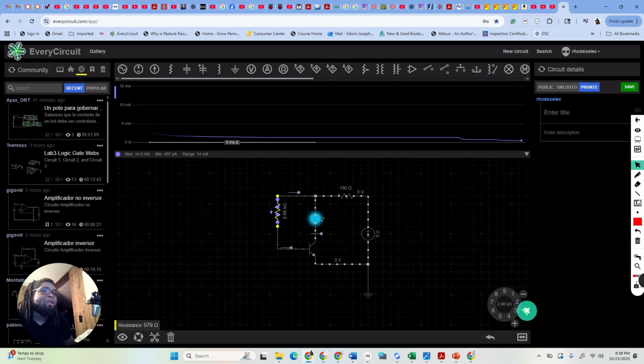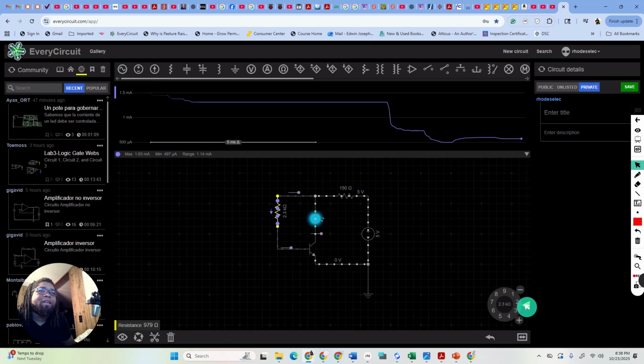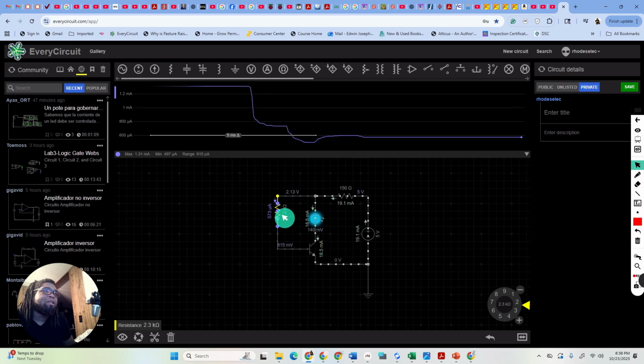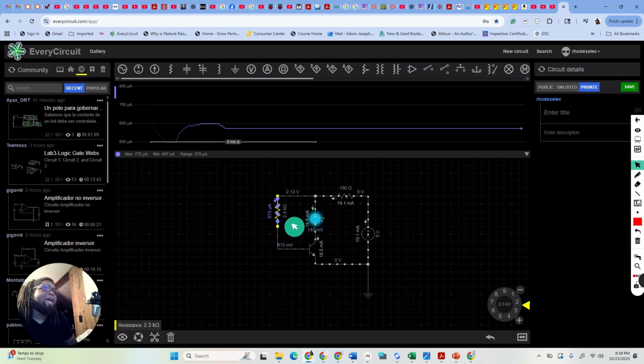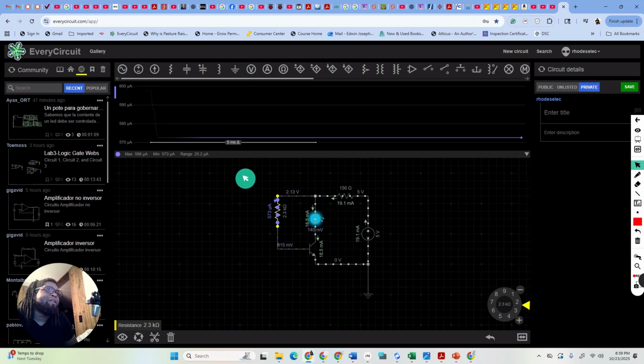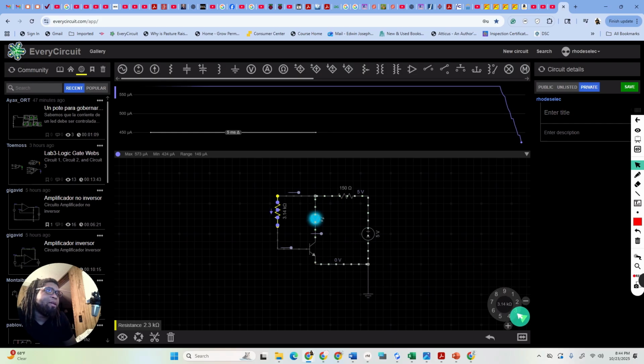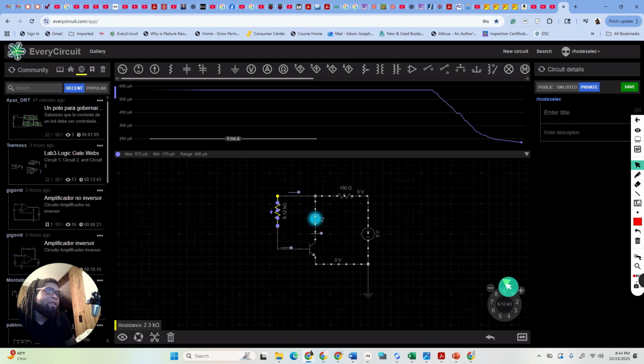If we get closer to our value, which was, I believe, yep, 2.3K, so a 2.3K resistor, now we can see that the current flows perfectly, with most of it going through the collector and emitter junction. So this is one of the reasons why some people like to look at a transistor as a valve, right? Because again, I'll illustrate this.